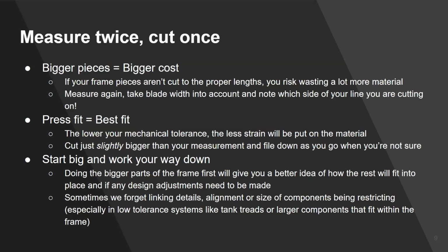One thing that I learned when I was first starting out and I didn't quite have that keen eye for getting the cut right the first time, even if it does waste a little bit of material, try cutting slightly bigger than your original measurement and then file down as you go, especially when you're not sure exactly how it's supposed to fit, or if the first piece you cut wasn't exactly what you wanted according to your design.